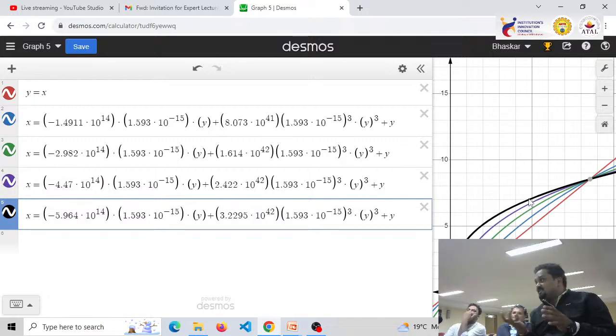Although mathematically we can see the signatures of negative capacitance in the ferroelectric, if you make a capacitor out of the ferroelectric material and put it in an impedance analyzer, you will see a positive capacitance. So in order to have a proof of negative capacitance, there are two ways. One is you check the total capacitance and the voltage drop. As I developed the equations for the FE-DE heterostructure, the capacitance in both cases, charge versus voltage and energy U versus charge Q, was higher. That is only possible if some negative capacitance is there. Otherwise it is not possible, because it violates the normal laws of thermodynamics and Kirchhoff's voltage law.